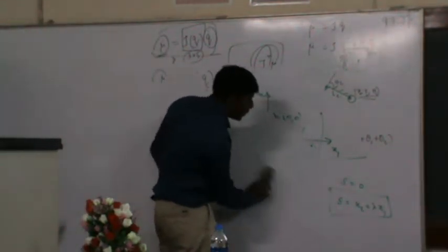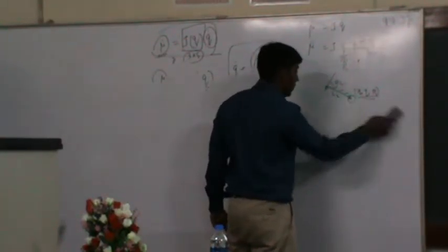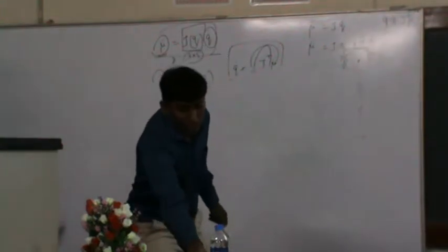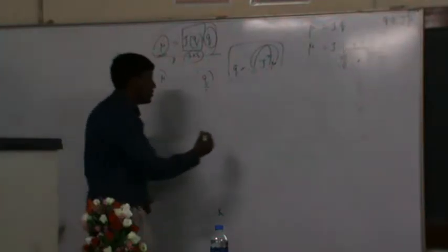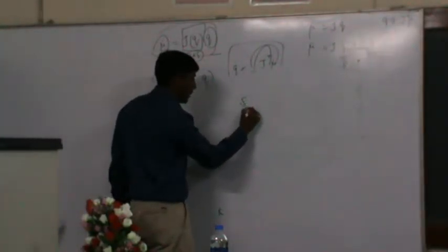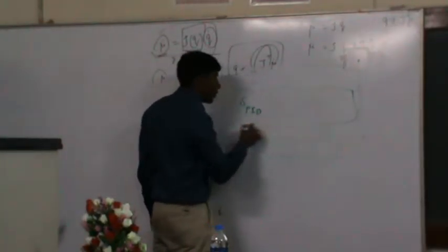This is what we call conventional sliding mode. There are other sliding modes also, like integral sliding mode and even second order sliding mode. All those things are there. So we have tried to use something like SPID, which is sliding mode with PID control.